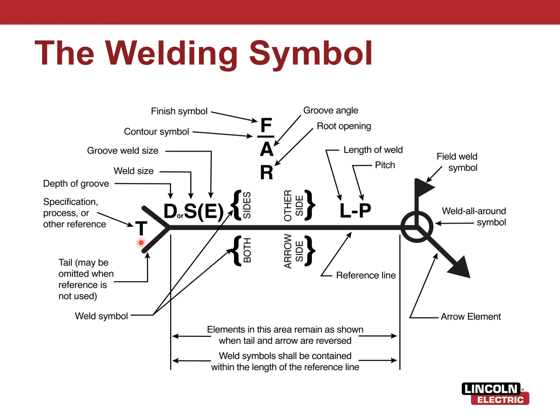But if you need a note, like maybe this is going to be a GTAW weld, and we want to denote that it needs to be that process, and maybe we want to put in there the specific material for the filler rod. Maybe we don't want to use ER70S-6, maybe we want to use a different grade and specify that. Okay, so that's what the tail would be for.